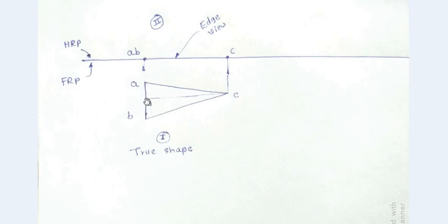So if you transfer this base AB here, and anyhow we will be transferring with the help of projectors, A point horizontally, B point horizontally, anyhow this one side of the triangle AB would be 40 mm. And it is given that the remaining sides of the triangle would also be 40 mm because it is an equilateral triangle of 40 mm.